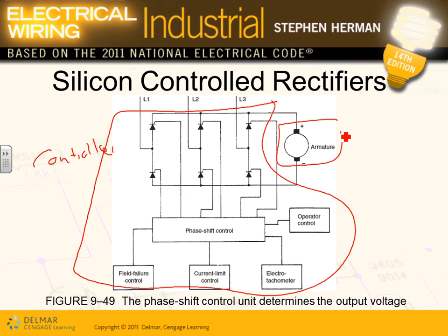They use these controllers, guys, to control the speed of a DC motor. If you have a DC motor in your machine, you're going to ask for a DC drive. You size the DC drive based on the size of your motor. That's your controller. You can control the firing and the voltages. By controlling the voltage, guys, they can control speed.